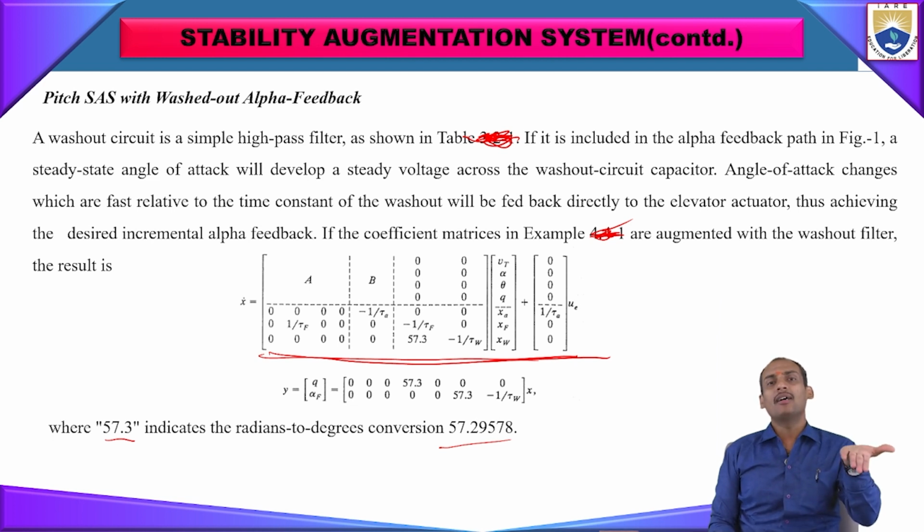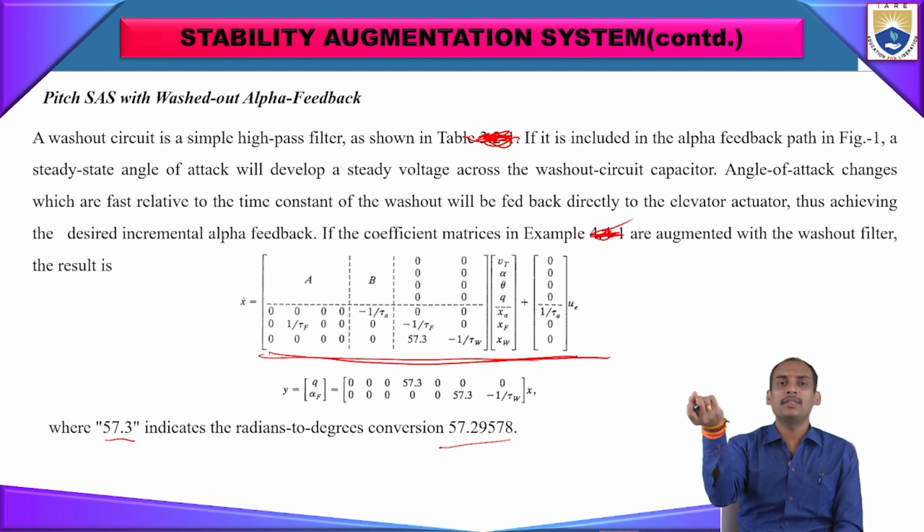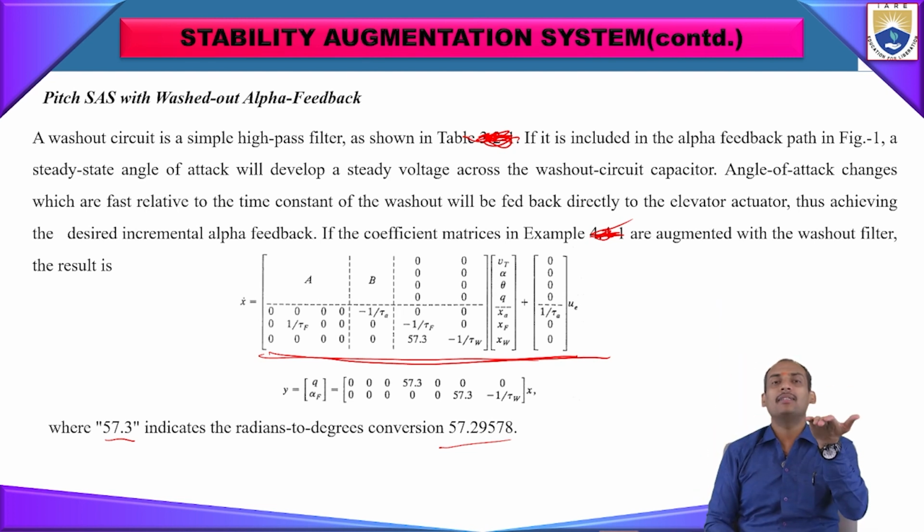Control augmentation means making the aircraft more controllable. So when we are using this SAS system for different control surfaces, like elevator and aileron, and for lateral motion aileron and rudder, and for pitch motion and axial motion flaps and elevator, when you are installing this SAS to these control surfaces, how the control surface movement frequency is obtained by using different integrators.